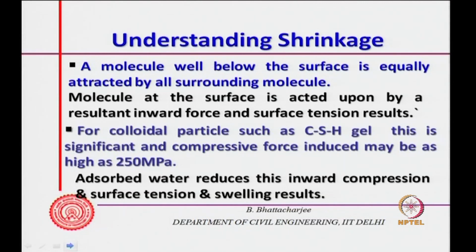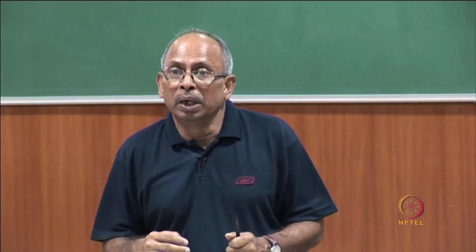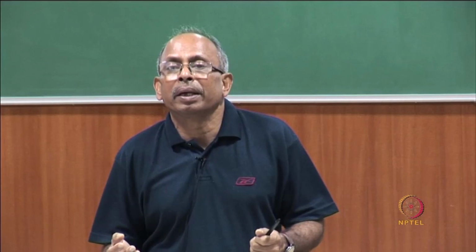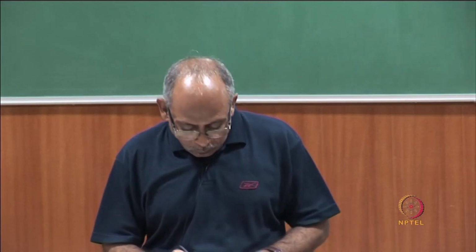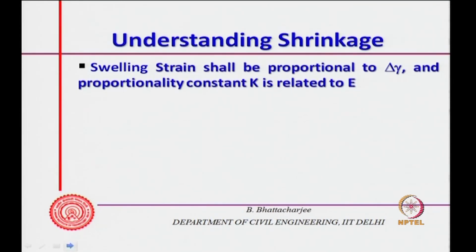So, what will happen? It reduces the inward compression. In other words, the surface tension of the CSH system has reduced. So, swelling will result. If there is no adsorbed water, then the molecules of the CSH particle system will pull the surface ones inside, and it would induce a kind of compressive force. Now, if there is adsorbed water, this compressive force will get reduced. In other words, surface tension would reduce and swelling will result. So, adsorption of molecules results in swelling, right.